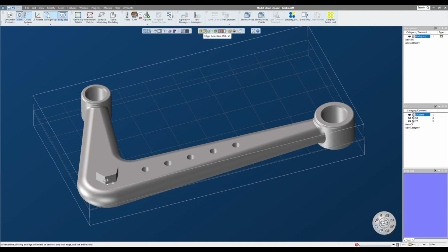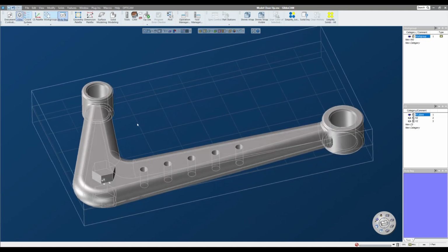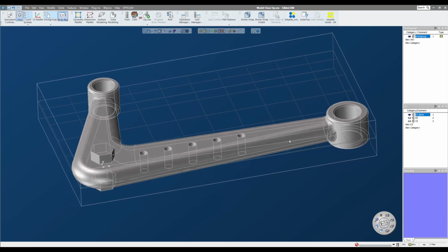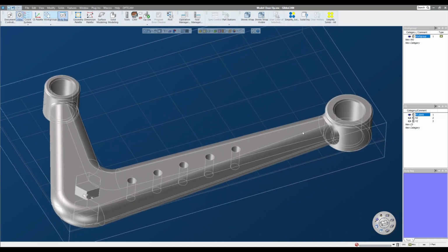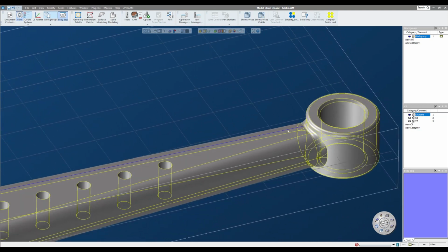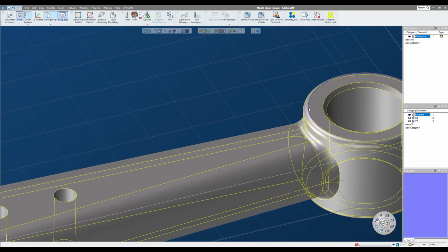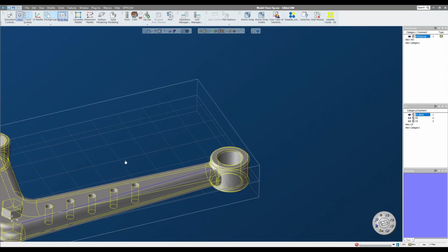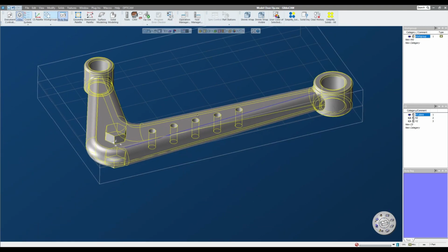The second tool we have is edge selection. Edge selection gives you a wireframe view of all of the edges of your solid model. So you can actually select edges of a solid model, extract the geometry, interrogate geometry, do different things like that. And again, you can hold down Control and select multiple edges of any solid model. Deselect by clicking off into space.